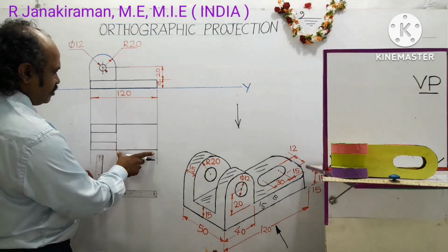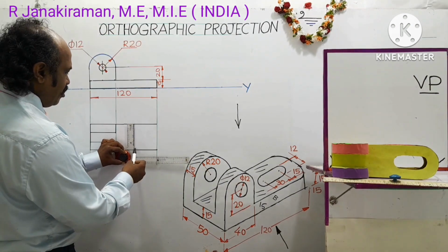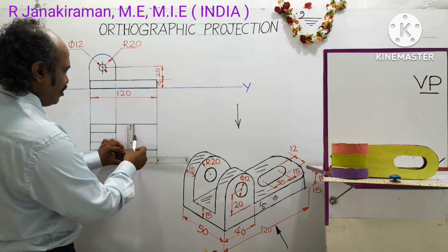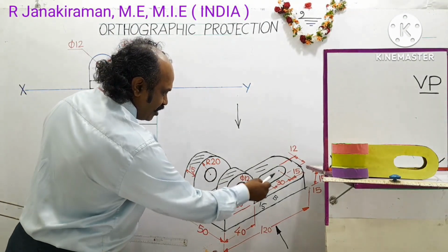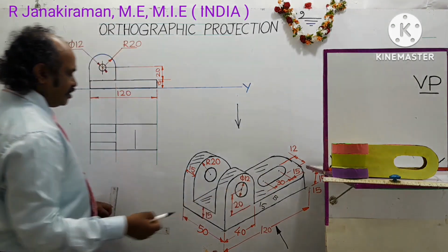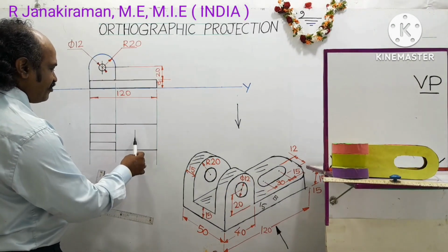Okay. Along this portion, locate this center point. You extend that along the center marked point as reference, draw a lighter line like this. Okay. So the distance between these two marked points, center to center, is given as 30 mm. Half of the 30 will be 15 mm. So right side 15 mm, left side 15 mm.